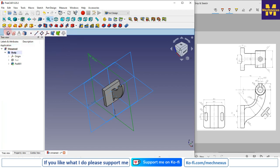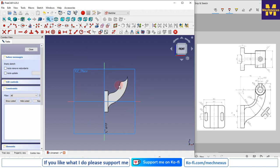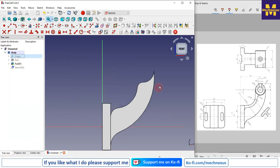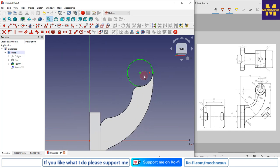I will move my icon here, so I will click on the sketch, select our mid plane, and then we will turn off our origin plane, and now we will project this arc, and diameter is 38, so this is the 38. So we will just make a coincidence constraint here, and we will constrain it.